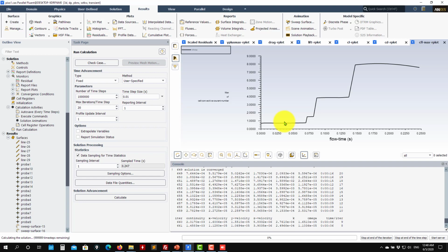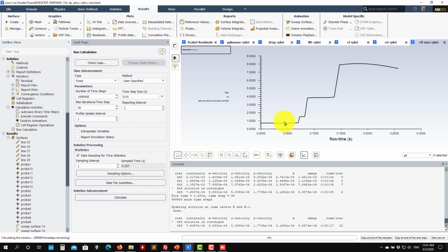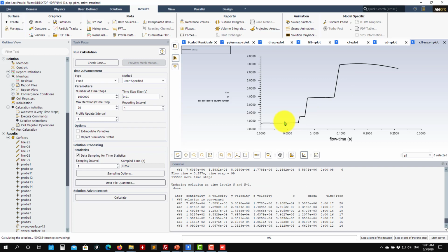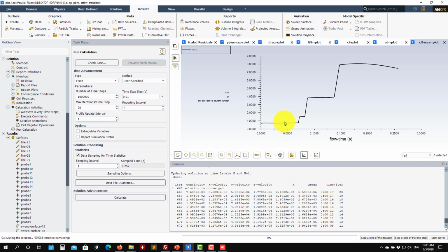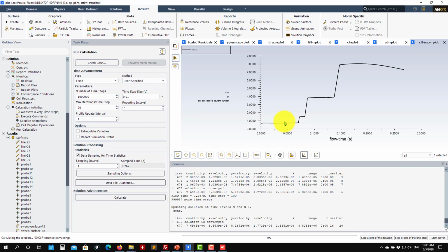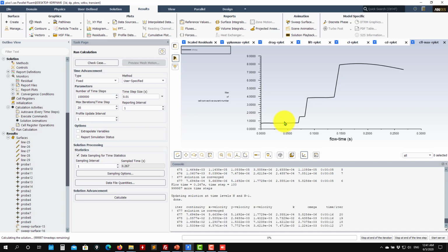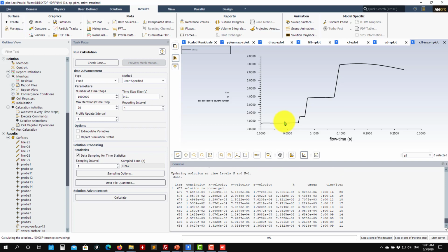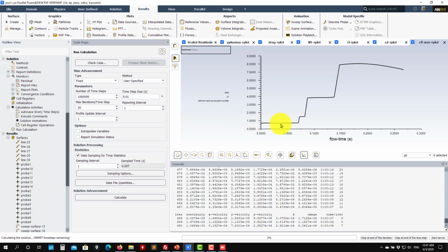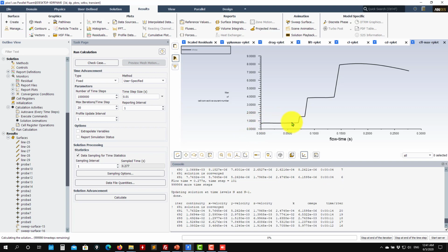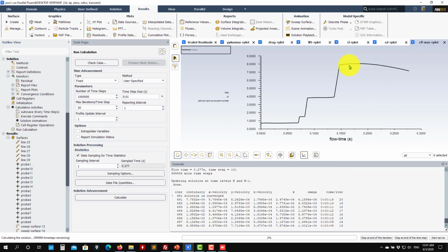Now you go 4 iterations, you multiply times 40, so from the computing time point of view, it works to use this CFL number. Still, it will be faster than using a small time step of 1 × 10⁻³. So my math was this one. So here it was taking 4 iterations, and here it's taking 14 iterations.